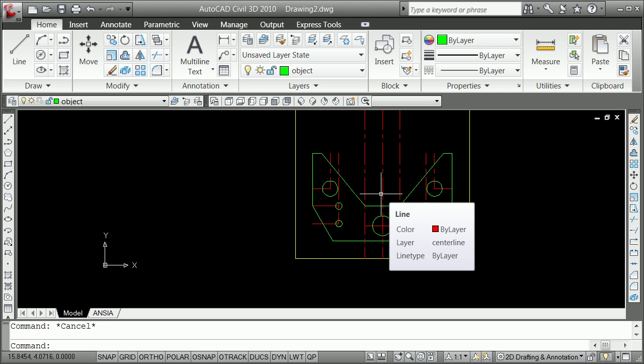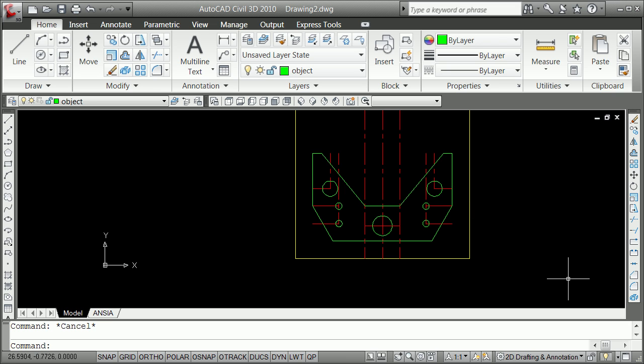Many of you have already pointed out that these holes are repeating shapes, so you would have made blocks for them. We're just going to think block until we all know how to make blocks. But anytime you see a repeating shape, it might be due to symmetry. It might be a hole. It might be a gear. You want to think block.